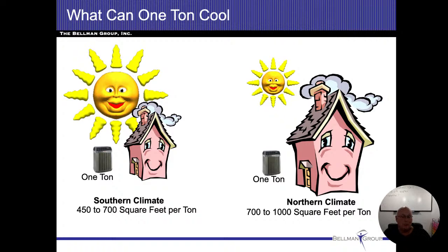All right. So a decent rule of thumb is about 1 ton for every 1,000 square feet. You really don't see too many systems smaller than 2 or 2.5 tons. Most of the ones we're going to run into, in the smaller homes, are going to be about 2.5 tons. In my house, I do not have a big home. We have a 2-zone system, so they don't really run all that much. It's roughly 1,500 square feet, and I have 2 separate zones, and they're both 2.5 tons.